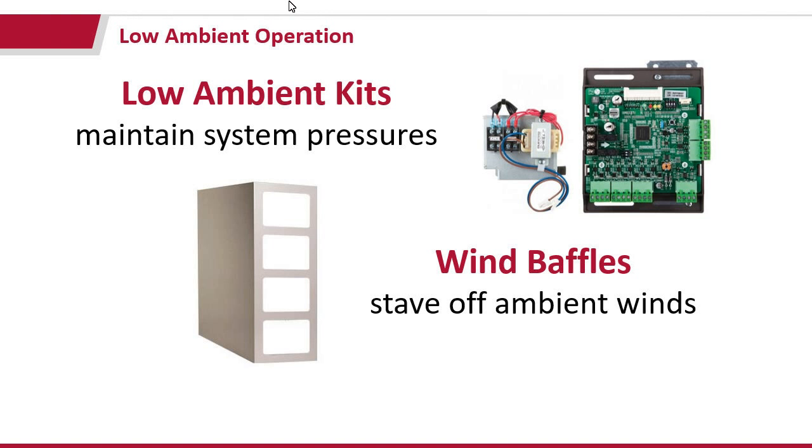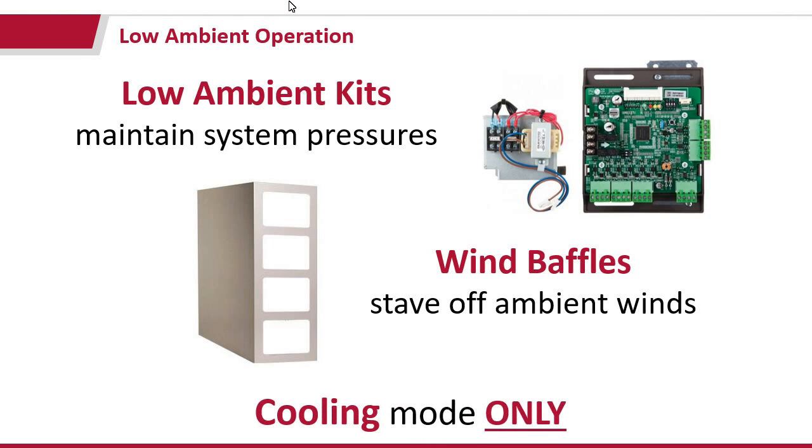Low ambient kit and wind baffles both allow you to take that cooling mode down to really cold temperatures, but you don't want to put this on a system where you're going to be heating, even for part of the year, because these systems are only for cooling mode. You basically just imagine that you put your heat pump in a box, and now your heat pump is taking all the cold that it can find inside, and now it's pumping it into this box.